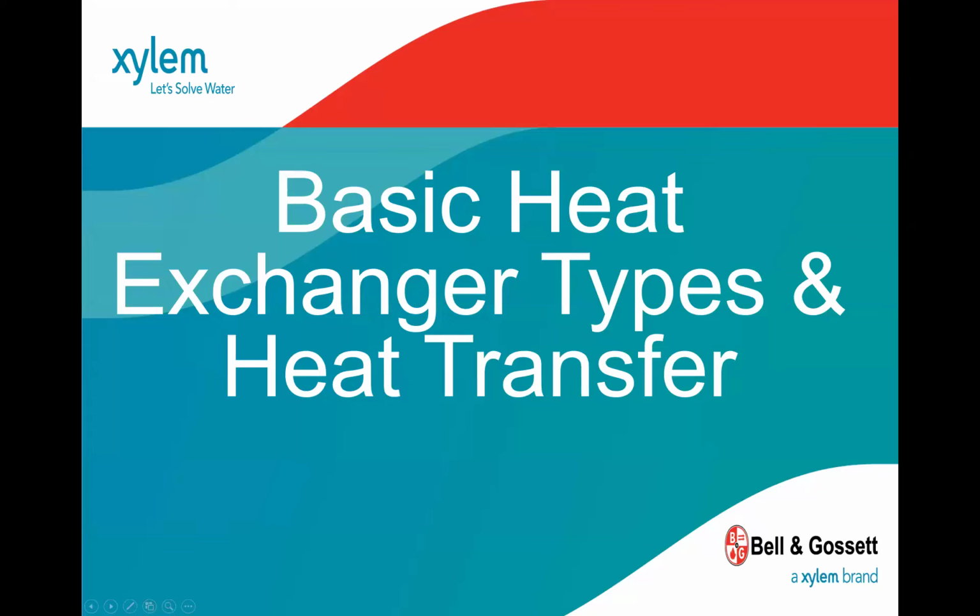So if you don't have that, there's always a test procedure. So in this case, it's plate and frame heat exchangers, and they provide a certification. It's AHRI 400, and I just highlighted a couple of these things on here, so that what people are claiming is actually the case.